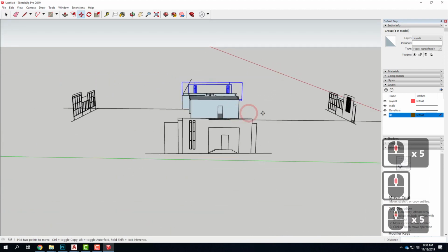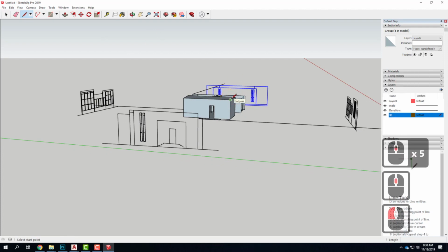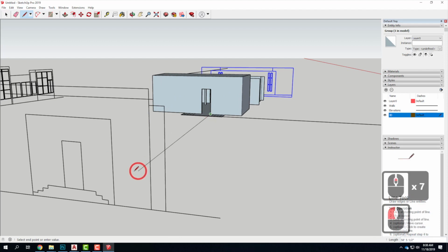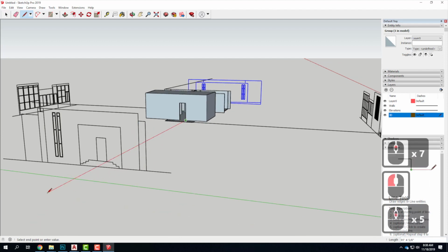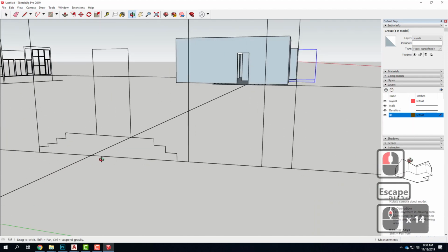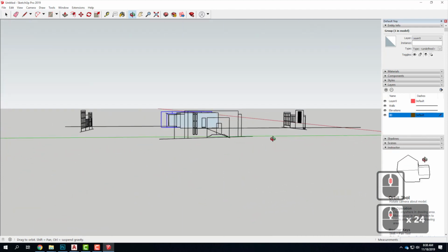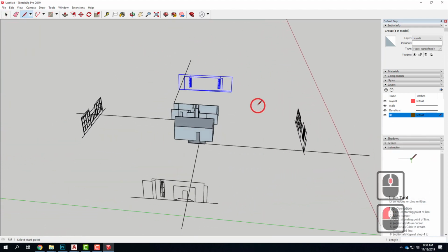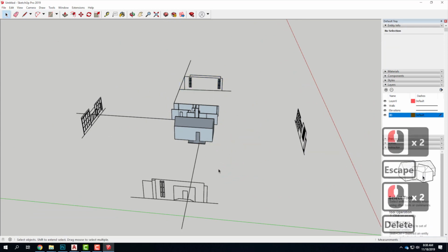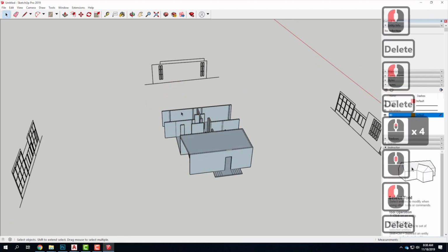This one over here, same thing, it has to line up. So I'll draw from right there, or actually I have the door, even better. I'll do it right from the door. Making sure I'm on axis. And yep, that one lines up as well. So once I have all of those lined up correctly, I can delete these lines because I don't need them anymore. And I can use these elevations to help me as a reference.